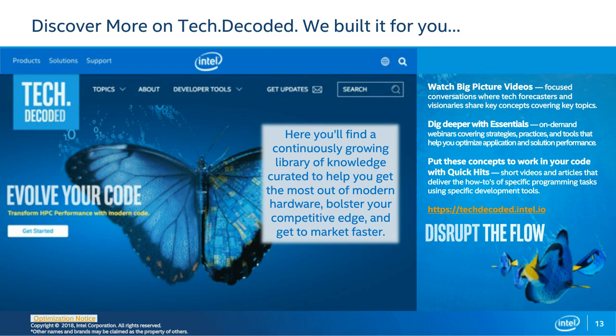All right. I'm going to finish with two more questions. Is there any prerequisite before using Intel System Studio for debugging? So is an Intel architecture machine, a connector, and downloading the tool enough to start? Not every Intel platform can support DCI, so you need to check if the combination of a platform and a connector, which is a probe, is in our support list.